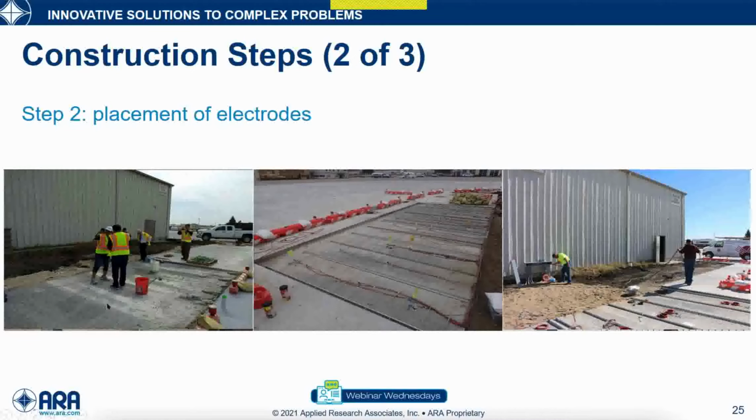So this is how it looks after we put the first layer, and these actual electrodes at the side, and all of the red wires, and all of these are sensors. So we heavily instrumented with strain gauges and moisture sensors to just understand the performance of the system. But if we need to build it again, we will not use all of those heavy sensors. We just use 1 or 2 temperature sensors just to monitor the temperature increase over time.